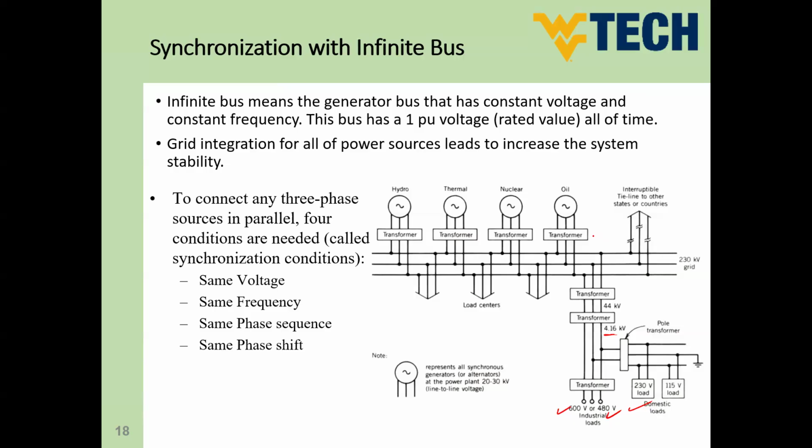is the reference value. So per unit means the actual value divided by the base value. Okay, so this is called the per unit system. Actual value divided by base value. So all the time, guys, since we generate the volt from any generator at the rated voltage magnitude, and the base value is the rated voltage magnitude, this would be 1 per unit.